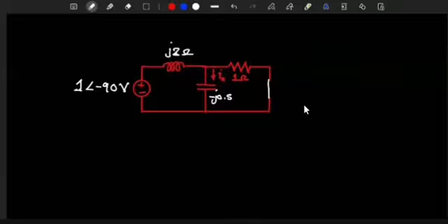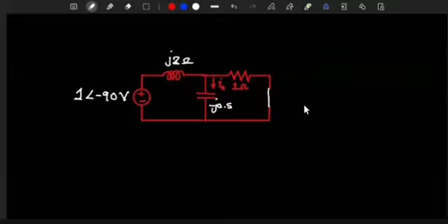Okay, so if we're using Kirchhoff's voltage law, how would it work? I want Ix, so I need to define a current that goes here. I can take this as I1, and the current that goes there I'll say is I2. At this junction, I1 enters. They may not write small letters like that. We've changed everything to phasor, remember? So even our Ix, when we find it, we're finding it in phasor form.